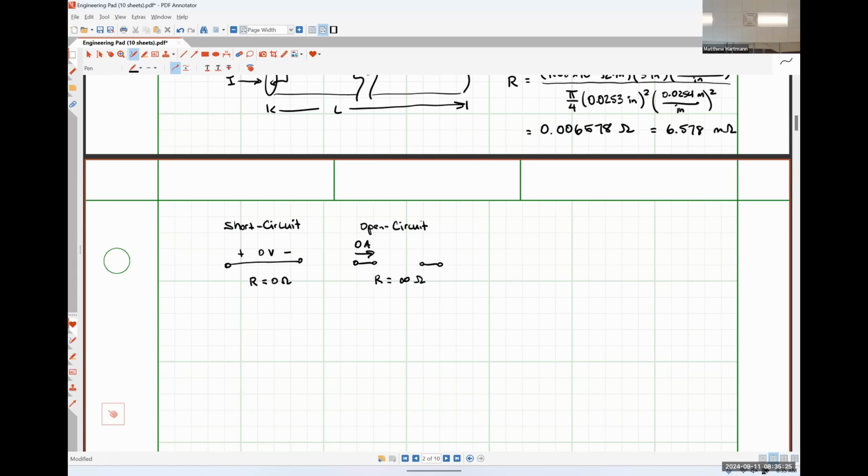If this outlet right here is an open circuit because nothing is plugged into it, but I take a piece of wire and get it really, really close to touching the metal contacts, we'll probably see some sparks as current flows. The voltage coming out of the outlet is roughly 170 volts as an AC waveform. If I get within probably half a millimeter or so, that's enough to ionize the air and cause current to jump across that small gap and complete the circuit.